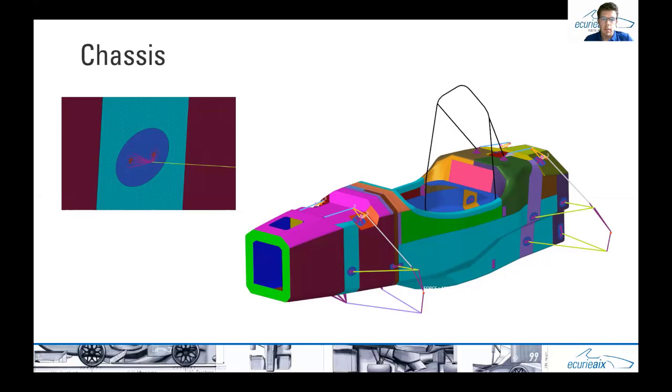After we finished constructing it, we removed all detailed parts which are too complex, which simplified the meshing very well. Then we declared some different zones in HyperMesh so that we can improve them locally more easily, because then we can assign a whole ply to the whole zone more quickly.